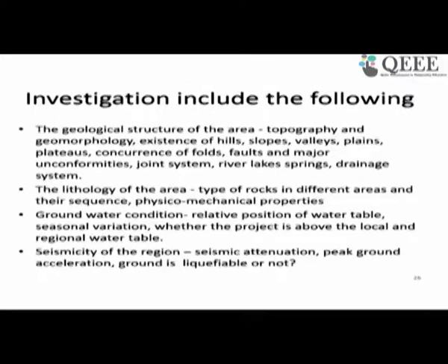So regarding the geological structures of the area, what exactly our goal should be is to get the details of topography, geomorphology, existing hills, slopes, valleys, various folds, faults, those are the information. Then we also try to find out the lithology of the area, groundwater conditions, and the seismicity of the region. In many cases, especially these days, earthquake analysis also plays a major role for the design of the structures. So, seismicity of the region also needs to be investigated.